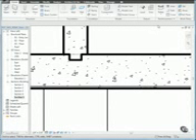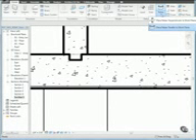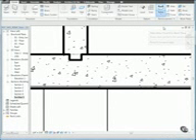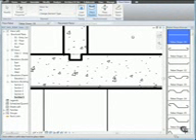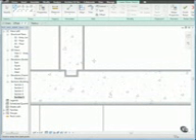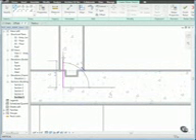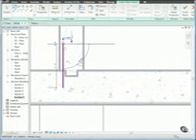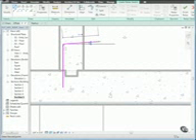From the Rebar drop-down, select Place Rebar Parallel to Work Plane, and then on the Sketch panel, click Sketch Rebar. Then, select the concrete slab as the host element. Then, sketch a rebar by clicking inside the slab first and then moving the cursor into the wall as shown. Then, click Finish Rebar.